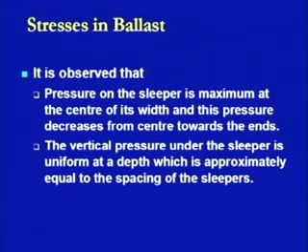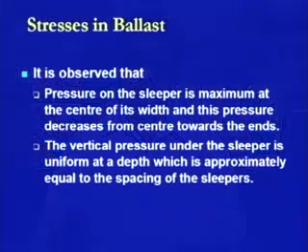What is observed is that the pressure on the sleeper is maximum at the center of its width, and this pressure decreases from the center towards the ends, and the vertical pressure on the sleeper is uniform at a depth which is approximately equal to the spacing of the sleepers. On the basis of this, we try to observe the stresses which are going to be induced up to a depth equal to the spacing of the sleepers.